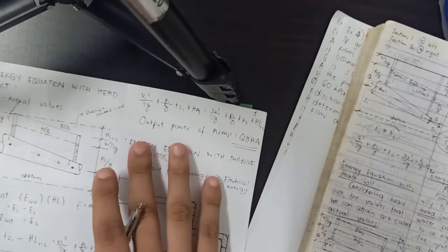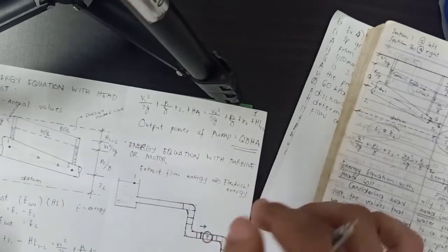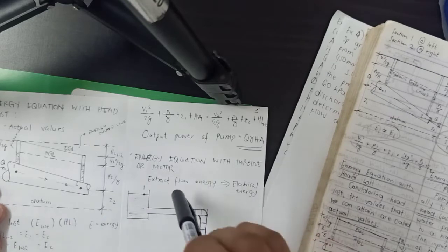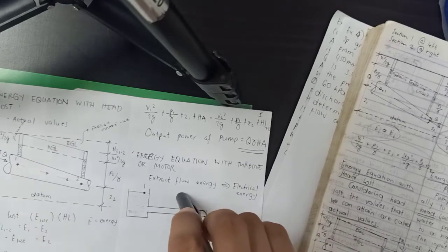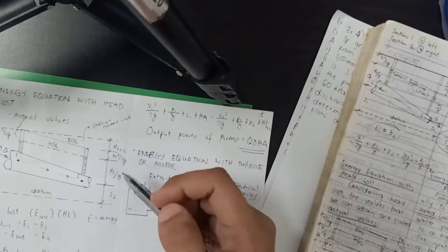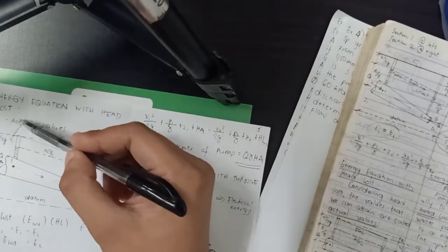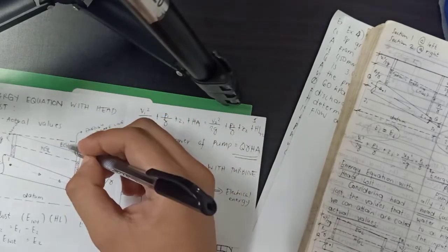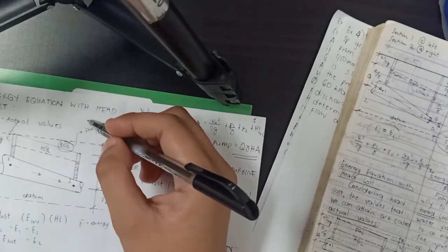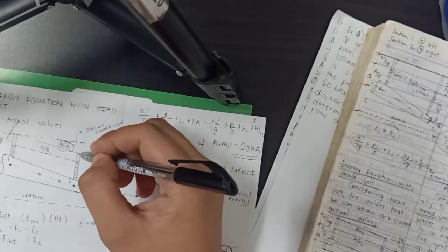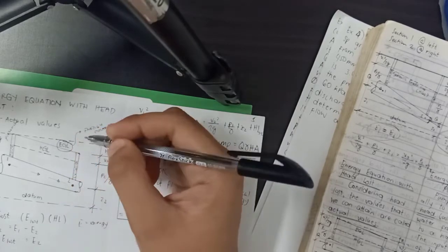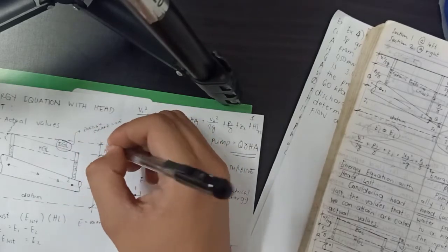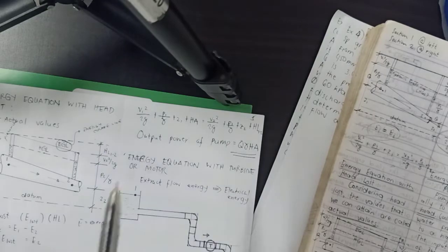Considering head loss, the values that we can attain are called actual values. So, if there is no head loss, they are only ideal or theoretical values. If there is, it is actual values. What is shown in the illustration? The only thing lost is the head loss. And here, the EGL is at the upper datum, since the piezometer is short. EGL is the energy grade line.